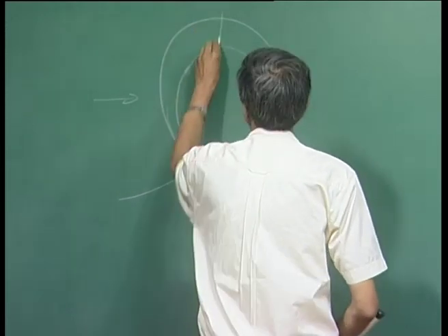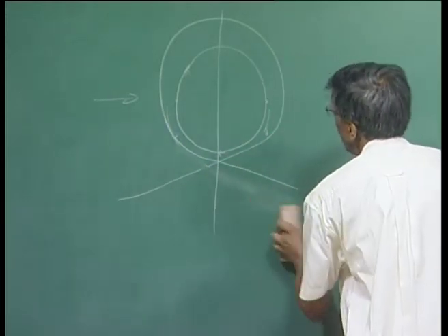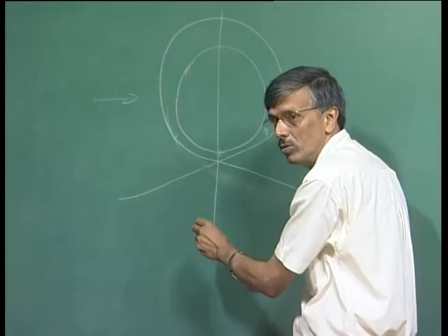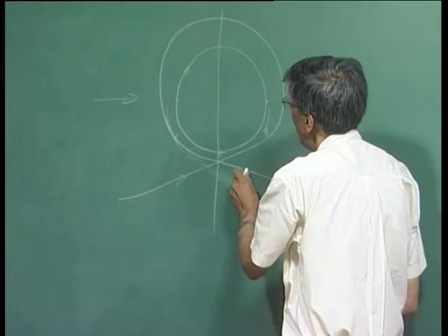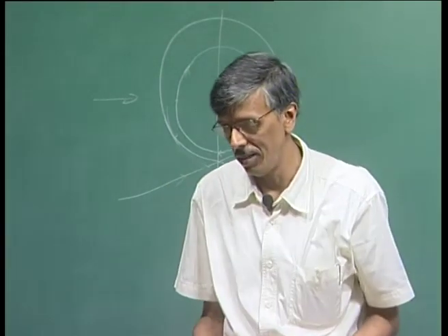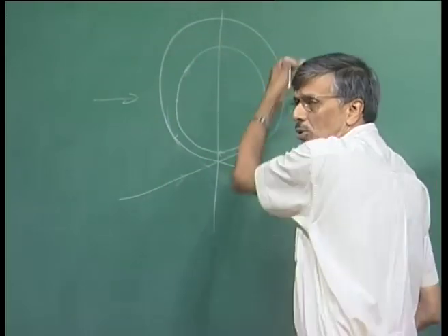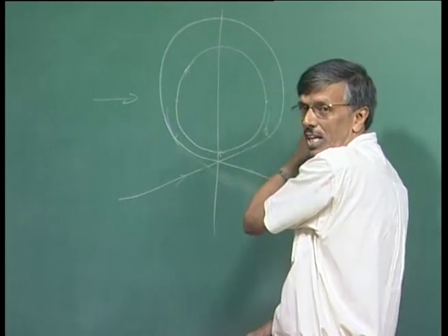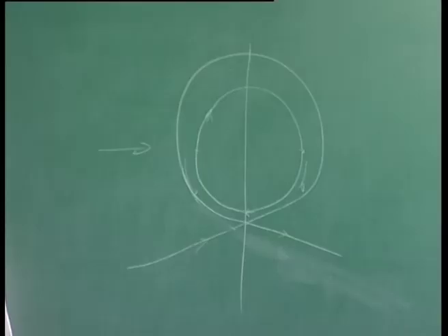it will be along the vertical axis, so it will simply come like this. And if you keep increasing this last quantity, then this keeps coming down. So you have a recirculating flow inside. If this is a streamline, for a long time, this was the heuristic explanation provided by Prandtl, that beyond 2 you cannot keep increasing the circulation because the internal flow is shielded from outside, although he did not consider the viscous nature, that is the diffusion of vorticity from inside to outside.